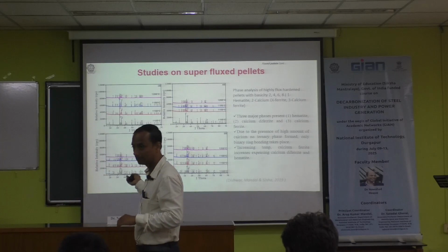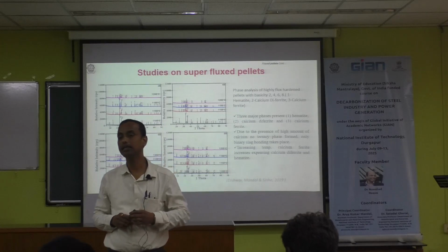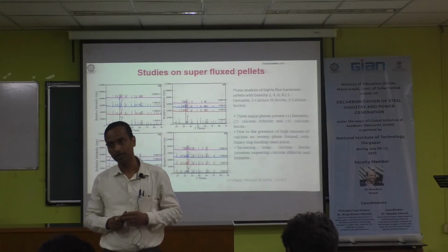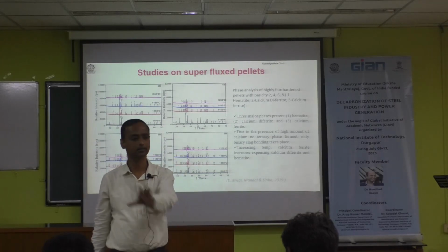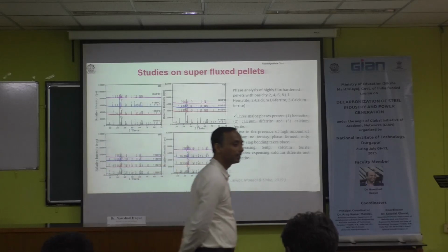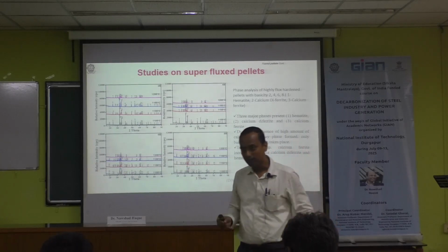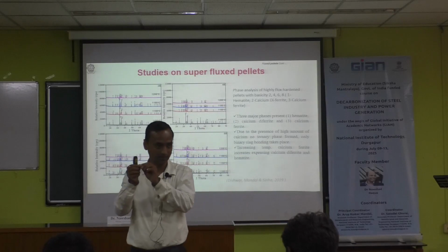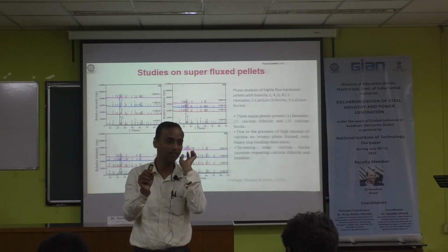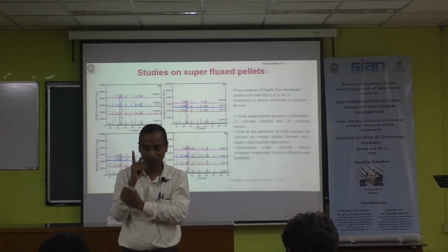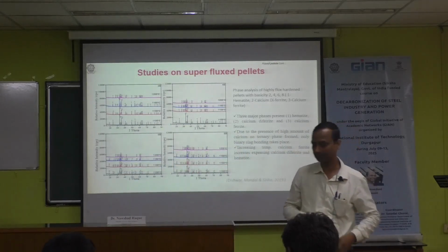Then we have done a lot of experiments and we have determined that the optimum temperature is 1180 degrees centigrade. If you straight away go for the firing at 1180 degrees centigrade, yes, you will get it. But the problem is that industry cannot fix it at exactly 1180. You have to give some range, like 10 or 15 degrees. In our laboratory experiment, if we set 1180, yes, it will maintain 1180. This is not possible for a normal furnace; it is possible for an electric furnace.